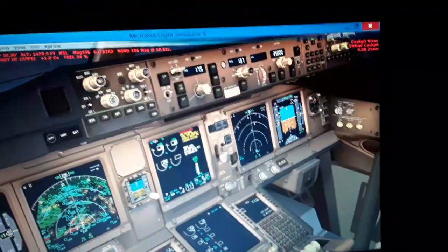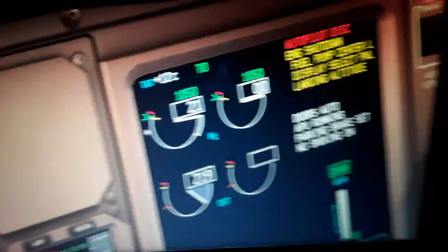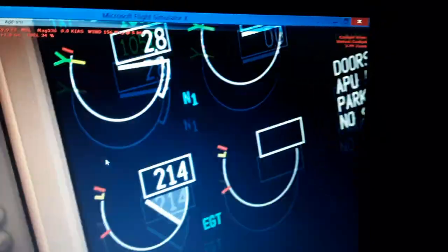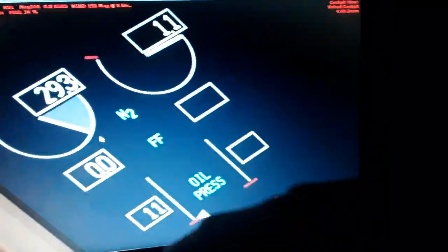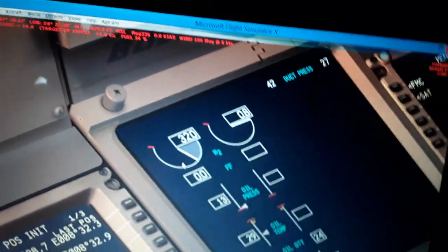The electrical, we have no engine left and right on the engines. Electrical power alternators, some hydraulic, maybe the engine bleeds here are off for starting the engine. Some isolation valves are reset, so we start the left engine starter first. Select the left engine. So you may see here we have the left engine N1 increasing. Also the temperature, here we have the N2, which is the high pressure, high speed rotor stage of the compressor and turbine of the turbofan engine.